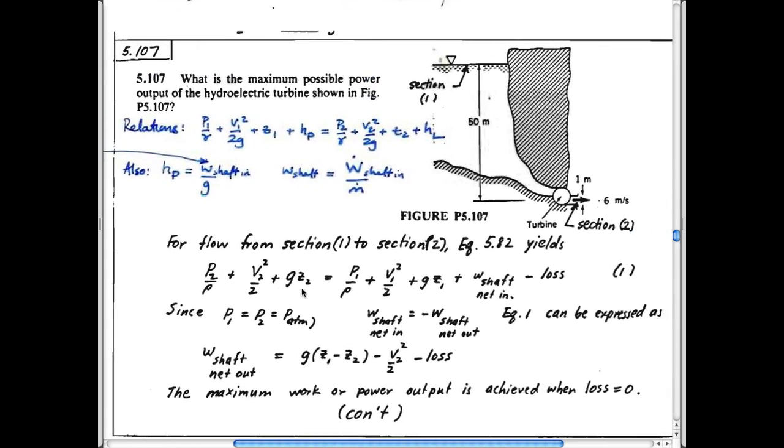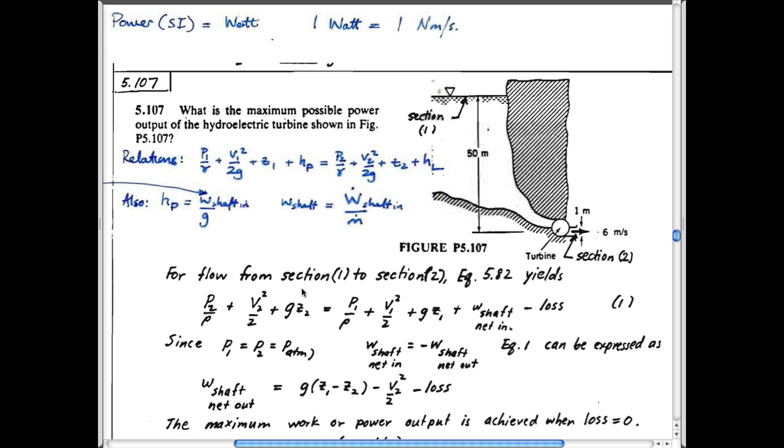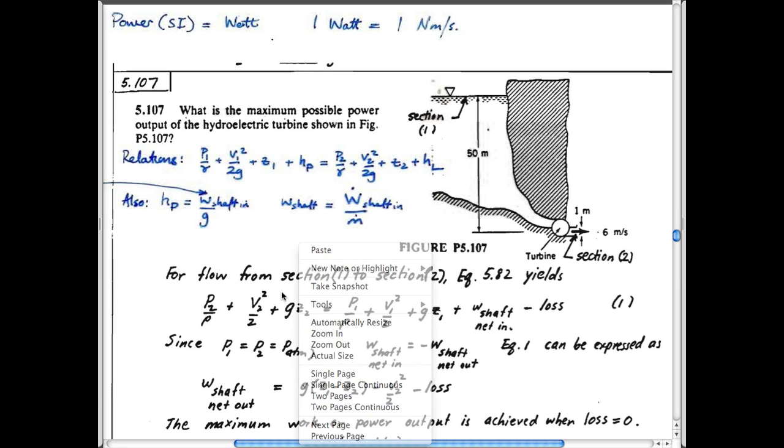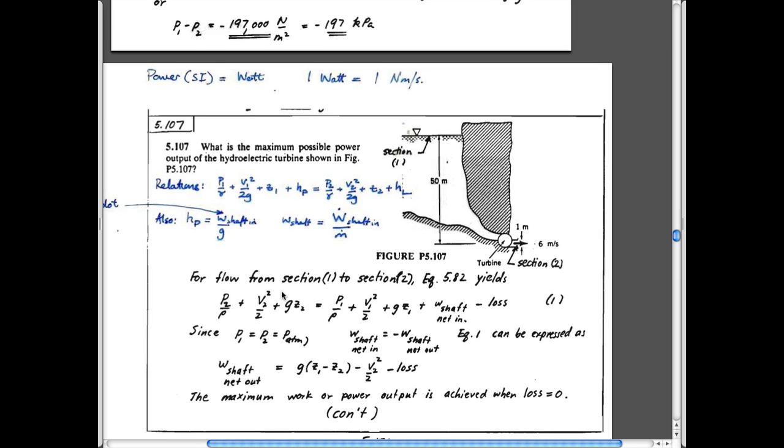A very practical, pragmatic one of a dam. The question is, how much power can you get out of a dam? Again, Bernoulli equation, choose where to write it: between point 1 upstream and point 2 downstream where this stuff comes out, where we know that the velocity is 6 meters per second. And we know the diameter, I guess, of the outlet.